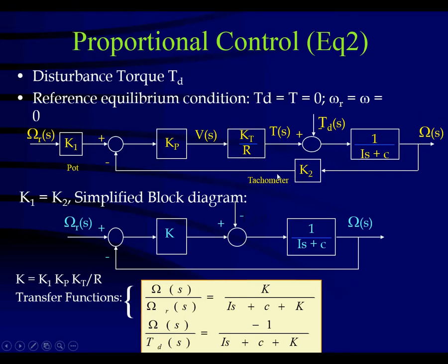This transforms it into an electrical signal and compares the other electrical signal with this here. So these little blocks are like analog to digital conversion. A lot of devices are like that. They measure a physical variable, but their output is a digital one. The temperature meters work like that. Speed control systems work like that.